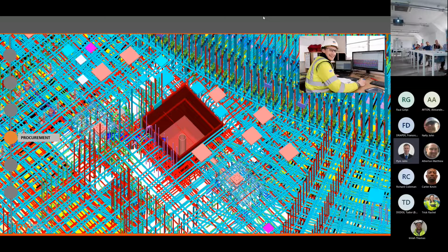So we can use that assignment of the pour ID, we apply it to the reinforcement, and then we can pick off the amount of reinforcement that's allocated to that pour, and we can call it off. So we're starting to really connect all the dots now through the initial design interface stage, where we're looking at this reinforcement, to applying it with the planning information, to then the extraction in the procurement phase.